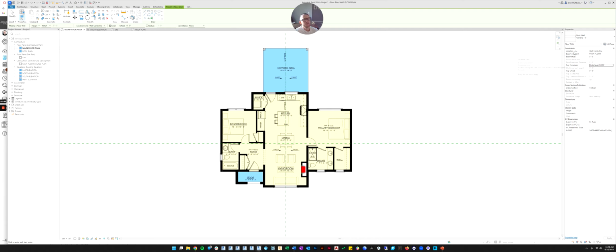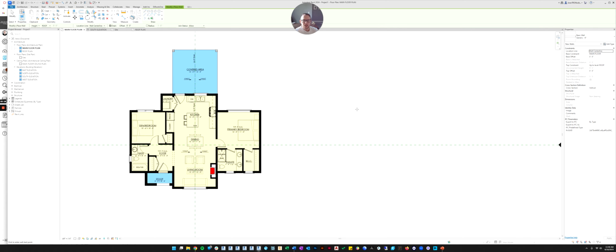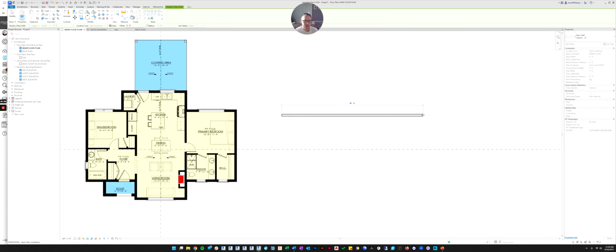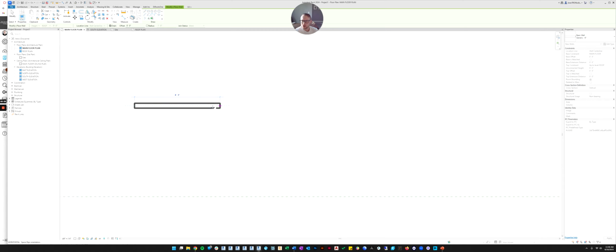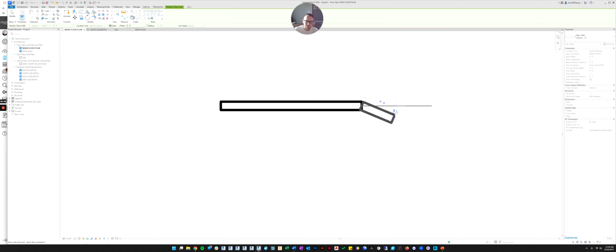The other thing you want to pay attention to is what's called the location line. It's hard to explain, so let me just show you. Let's leave it at center wall line right now. That's the default, the center of the wall. So it's basically saying when you draw this wall, the blue dotted line that you're drawing is in the center of the wall.